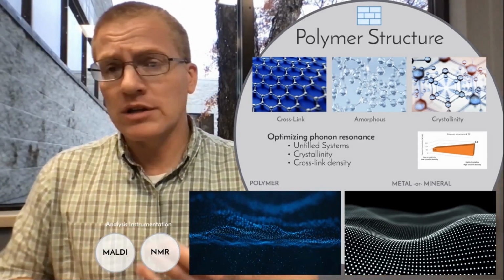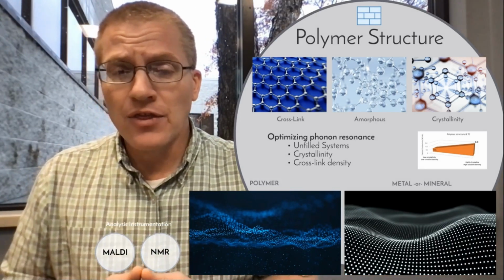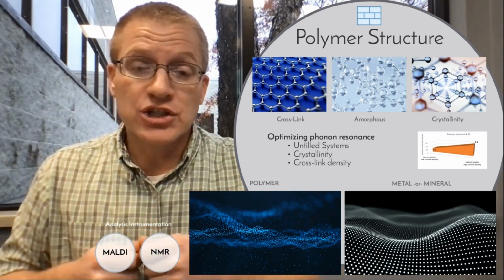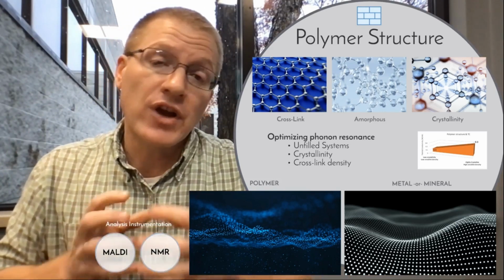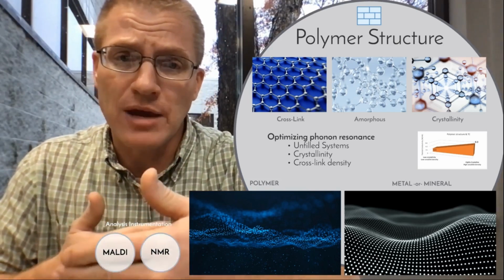So it's number one, cross-link density, all right? So in the graphic here, the higher the cross-link density, the more all of those molecules are chain linked together, the more they're in intimate contact. So a wave is going to transmit much more efficiently through them.